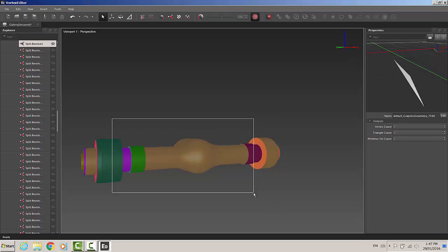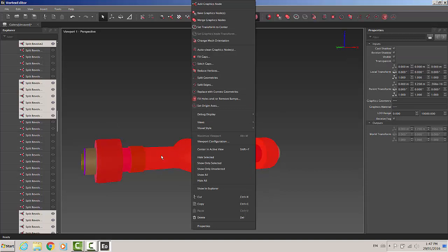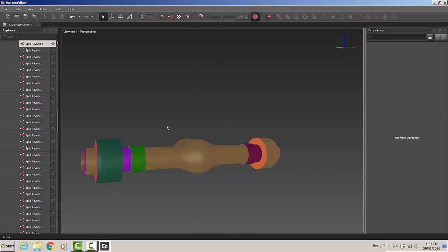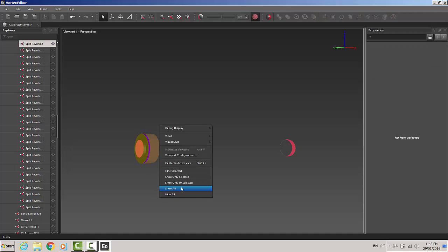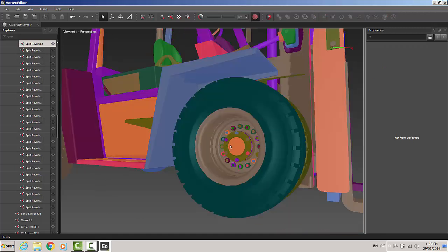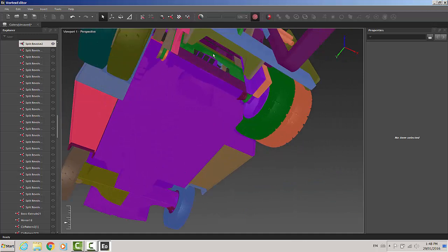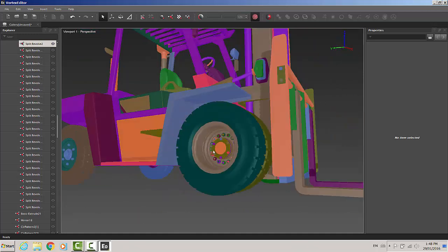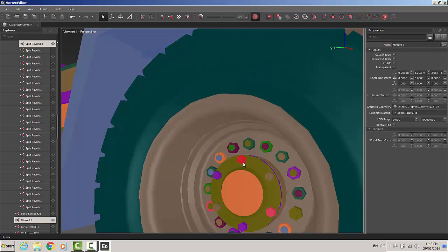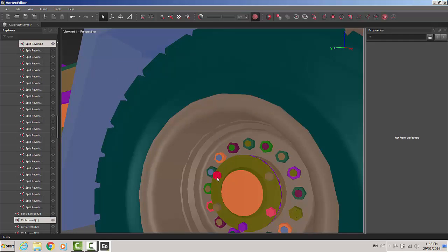Much better. This time, the axle has been broken down into smaller nodes. I simply select the nodes that I do not need and delete them. Bringing back the entire model with the Show All tool, we still have our end cap, but the hidden axle is gone. We can also directly select nodes and delete them, or move them, or duplicate them as we need.